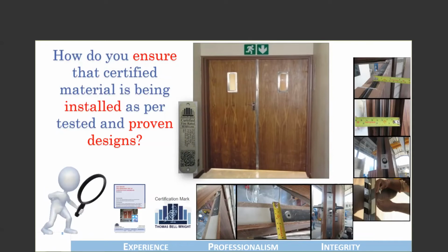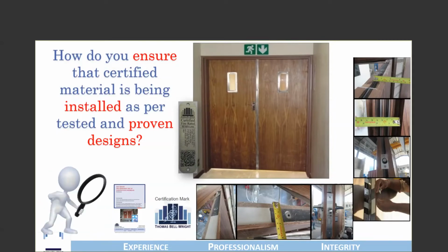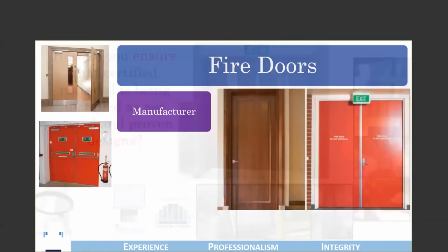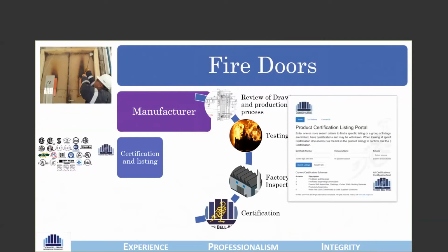At this stage, I am not delving deep, but there are published standards like NFPA 80 for fire door inspections or installations, which define very specific methods to bring about the assurance which is badly needed. So I am summarizing this in a quick block diagram wherein the manufacturer would typically conduct several fire tests to arrive at not necessarily one, but several certifications and listings combining different designs and different materials.